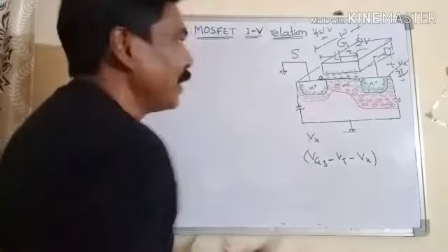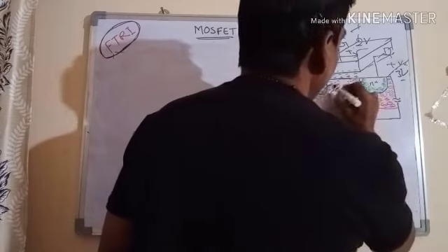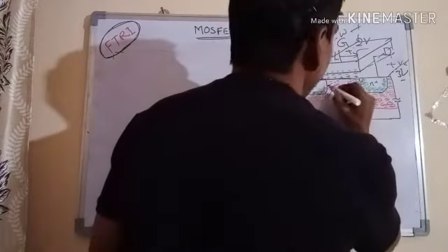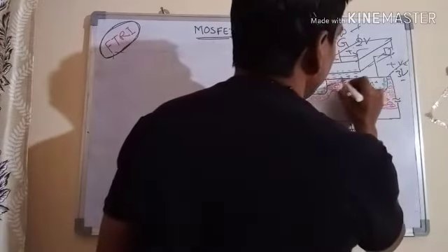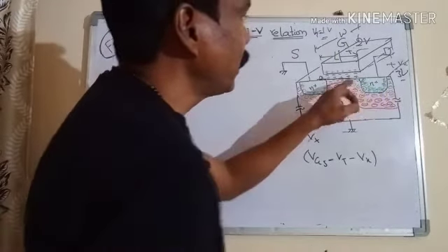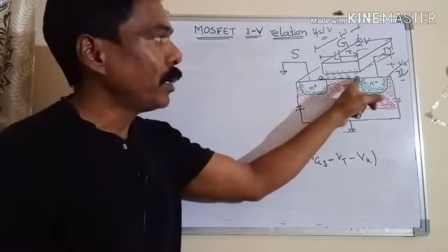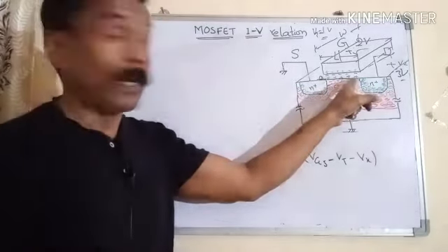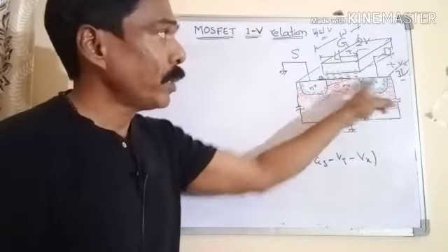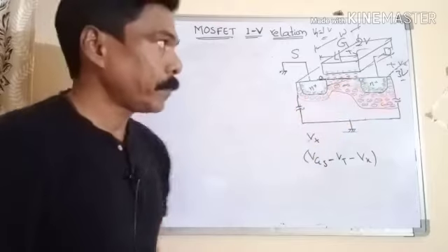So the channel support voltage becomes 0 at the point where Vx is 1 volt. That means the mobile electron charge will become negligible there, and later there won't be any mobile channel, but the electrons will be swept to the drain with the saturation drift velocity.